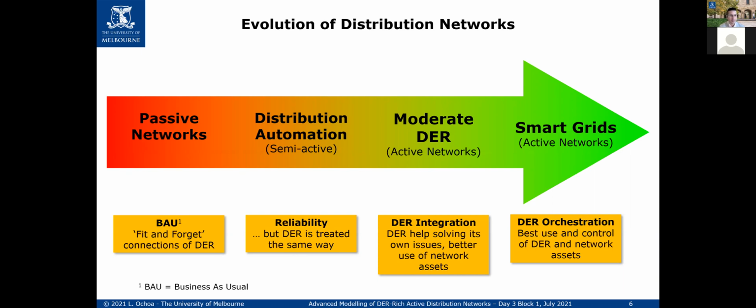So you make the calculations of what you can connect as your wind farm, two decades ago, and you tell the investor, this is your maximum. If you're going to connect more, you need to pay for the upgrades or some part of them, and that's it. The idea is that once you fit that wind farm, you forget about it. You don't need to control anything because it just works for the maximum generation and minimum demand, so for the worst case scenario.